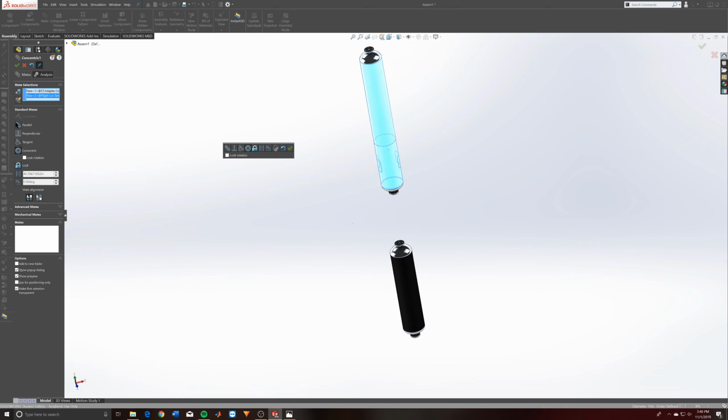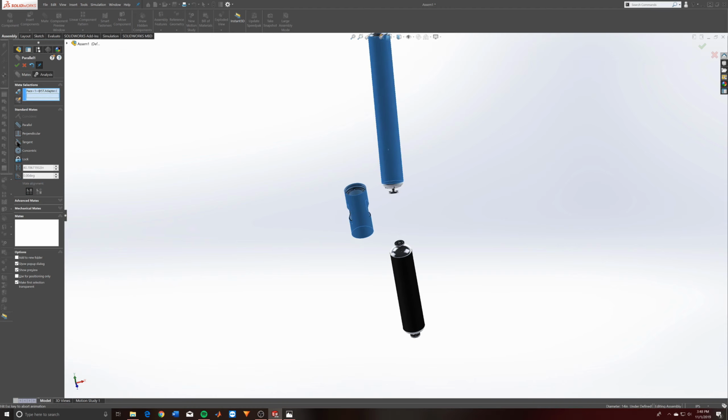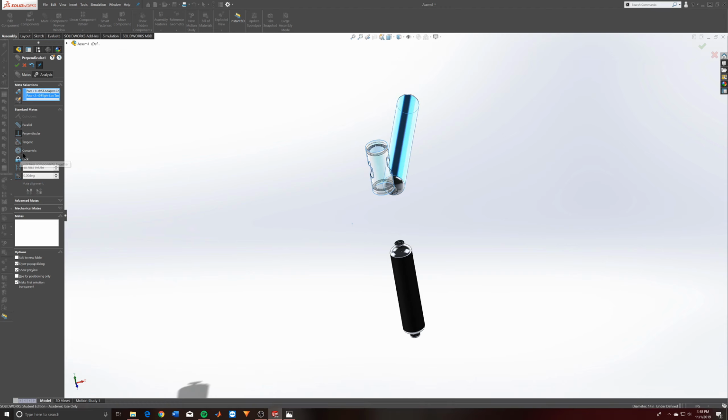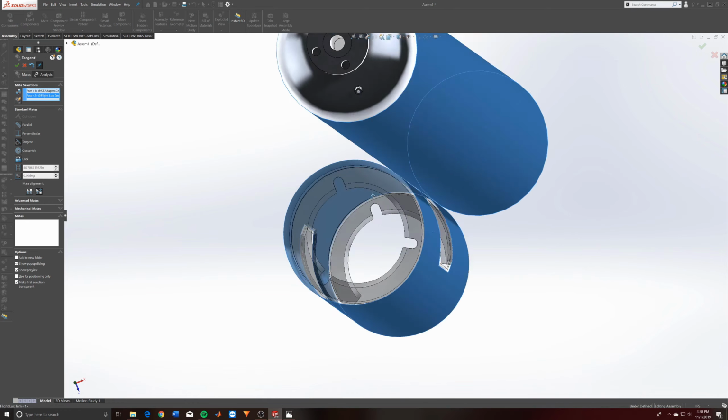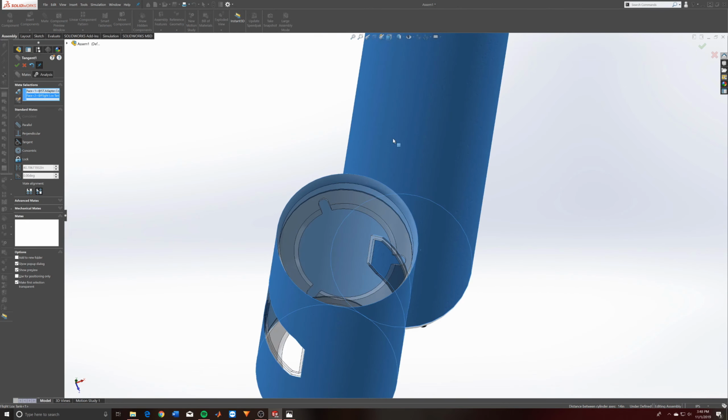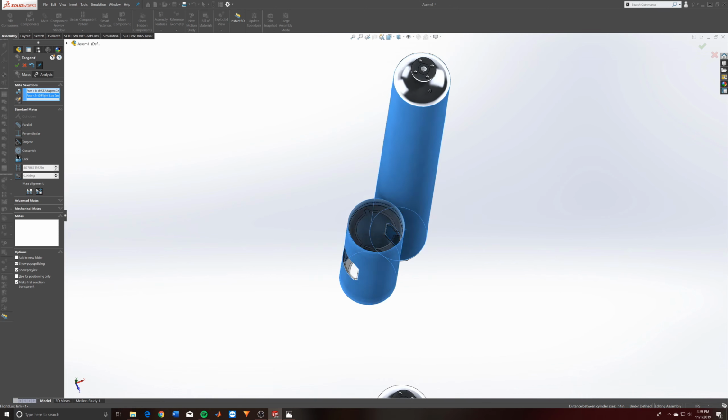Now, as you can see on the left-hand side in the window, it has concentric clicked. Now, you can click other tool properties, I guess these features, and it'll give you different mating options, or different ways of putting it together according to whatever you picked over here.